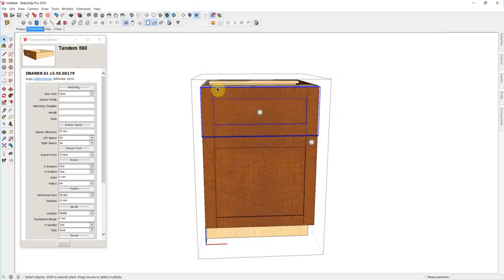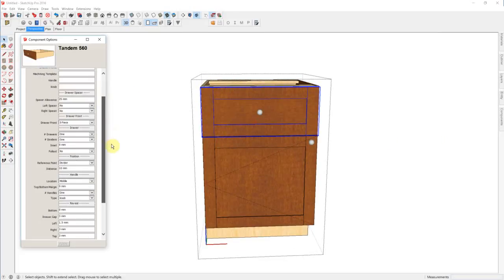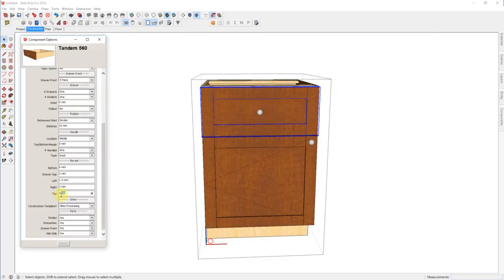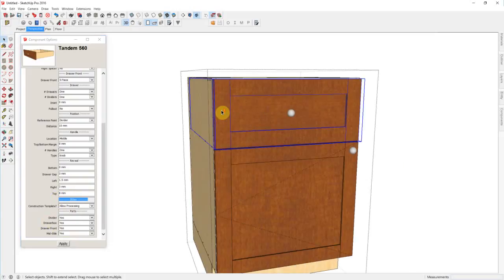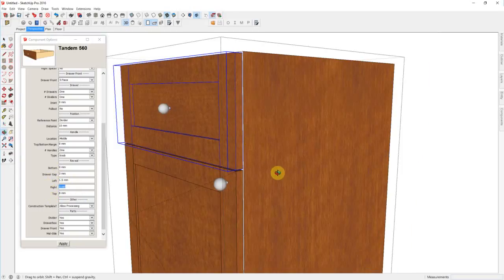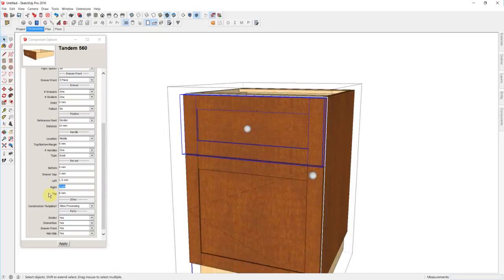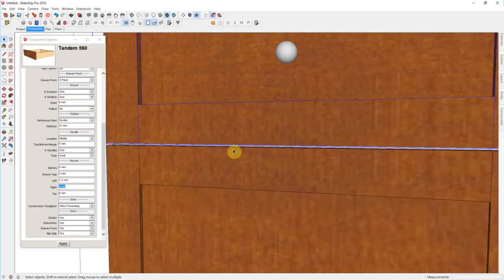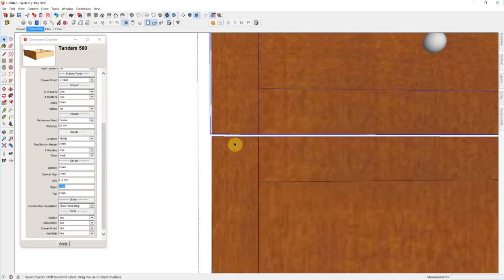So when we're at the top of the cabinet, I am using a 3mm reveal. Now I'm going to change that to 8mm. On our unfinished end, we're using a 1.5mm reveal and a 3mm reveal when we use a finished end. I have no bottom reveal when I am joining two cabinets or two parts together vertically. There is a gap,